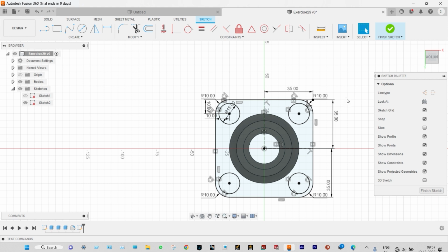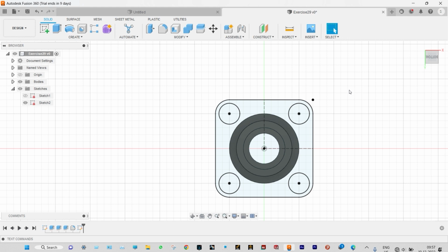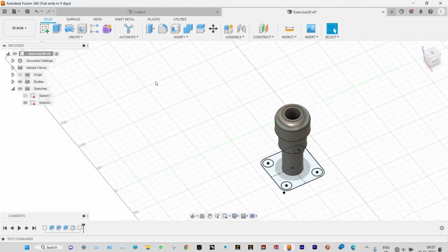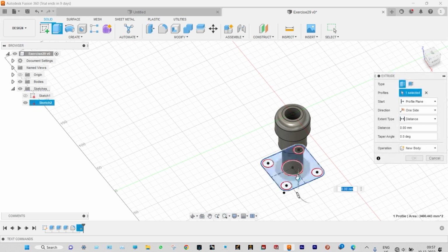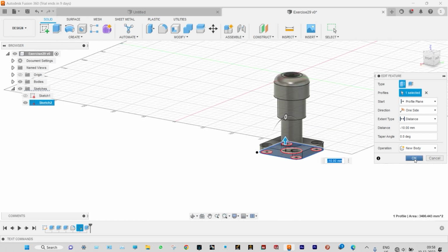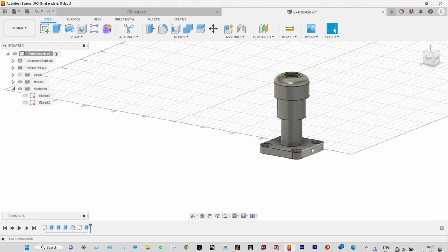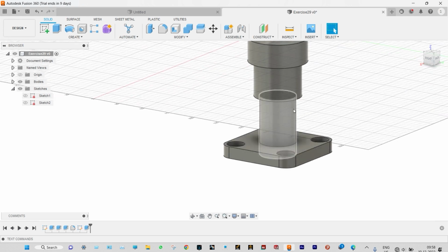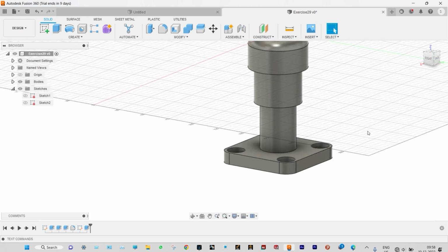So we need to finish the sketch, and that to be extruded to a specific depth. Right, starting with extrusion. So as a shortcut, enter Q, and we can select the specific areas to be extruded. Right, and depth of extrusion will be actually 10 millimeter. We are considering this one to be made up of a new body. Okay, done. Now the same thing to be provided at this location also. So for that we are having different operations, like we can provide this one as a linear pattern also, right, or we can copy the same thing and move it to a specific location.